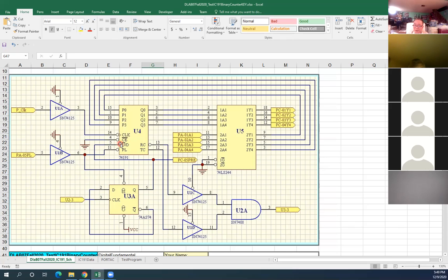Okay. When you're counting down, that means 15 down to 0. Then you get the pulse coming out here to U2 and it applies the clock to U3 pin 3. Then the output will toggle. That means pin 5 now will be 0. And 0 will be telling you now you start counting up. Okay? So it counts down first and counts up later automatically.